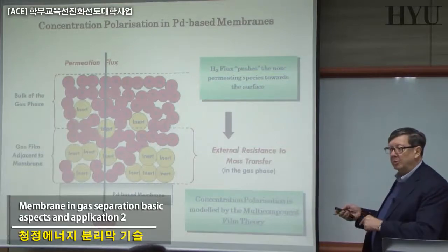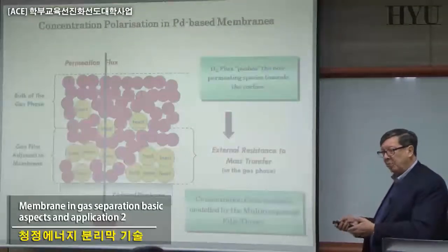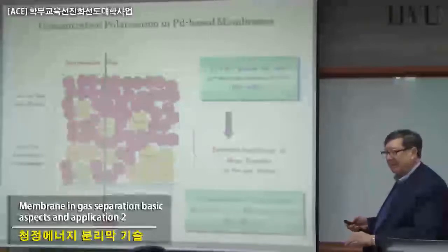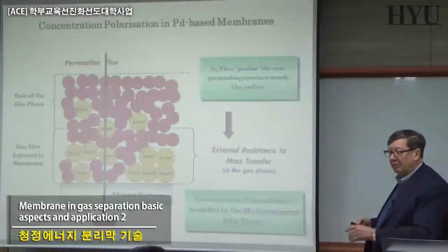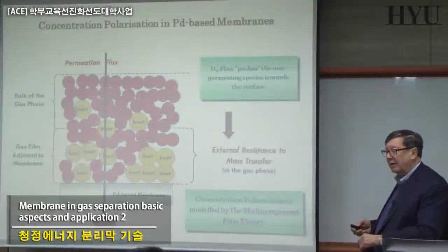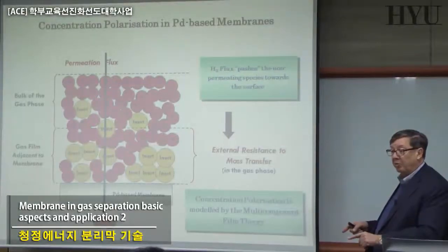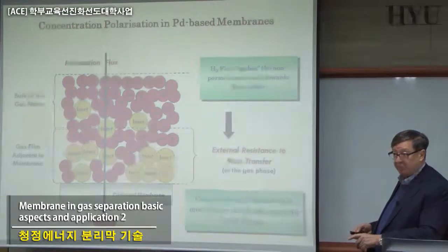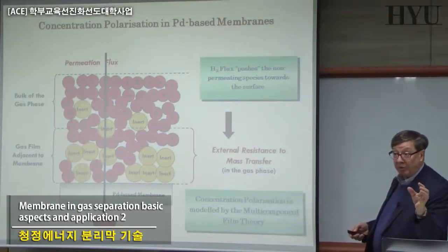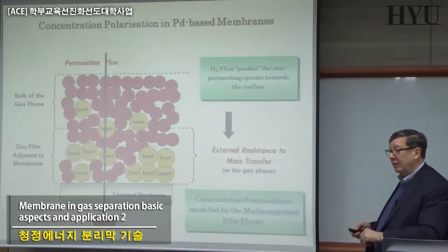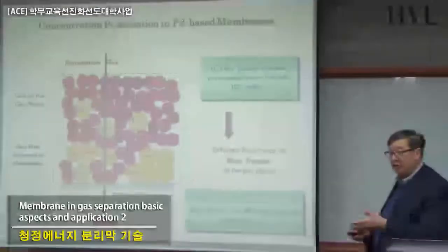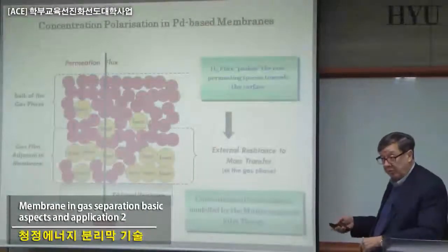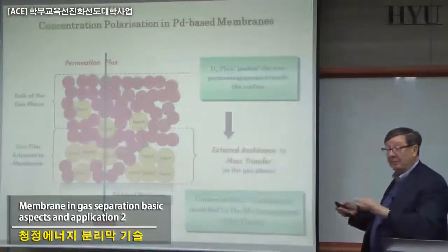Everybody was looking at the permeability, the intrinsic properties of the membrane, selectivity, permeability, etc., but a little bit less at the problem that can control overall performance, particularly in reverse osmosis and nanofiltration, which are the osmotic phenomena in that case. That means the increase of the concentration at the interface, related to the selectivity of your membranes, can kill the process.